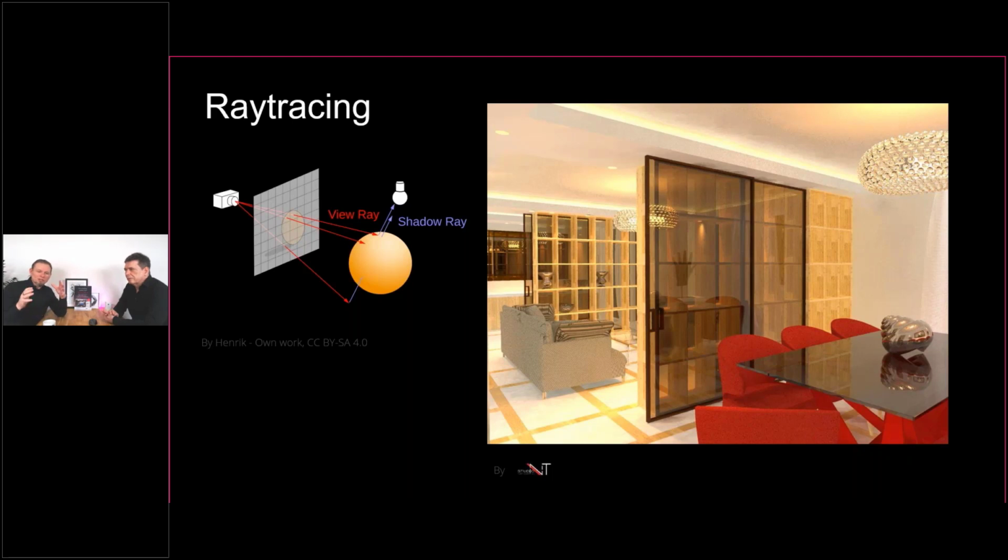What you visualize is in a way ray traced in real time, but primitive and without any values, just to give the look and feel of a real scenery. It's not calculated to the last surface. It's just to give you a nice impression of the scenery with everything light could offer in terms of reflection and transmission. Quite nice work, but this is something you need to consider as a user.